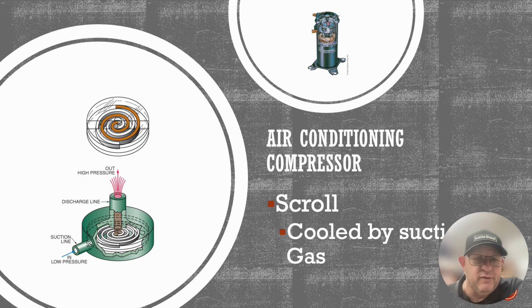The best compressor for handling liquid refrigerant is the scroll compressor. You can notice that on the side of it, there are no accumulators anywhere on this compressor. Now, they do protect it in a way. Copeland will say it's not a liquid refrigerant compressor, and I would agree with them. It's a vapor only pump, but the scroll set on the inside of it can separate, causing the liquid to flash into a vapor, protecting the compressor from damage from the liquid refrigerant.